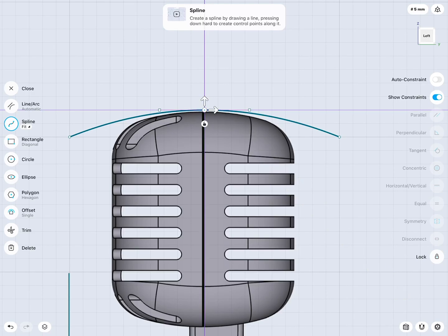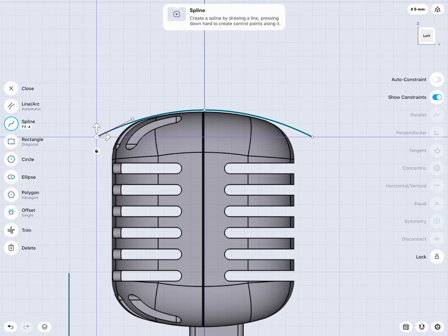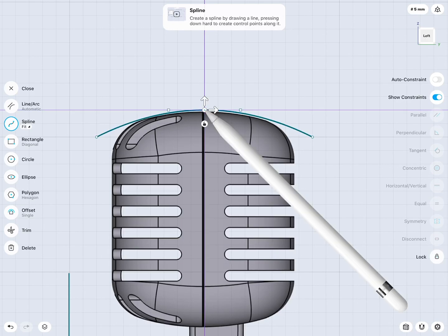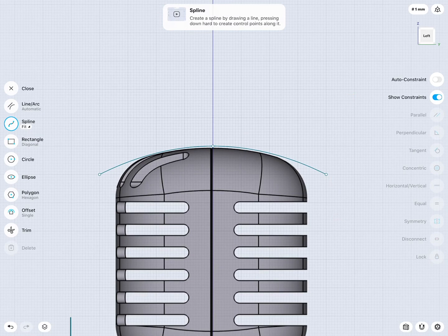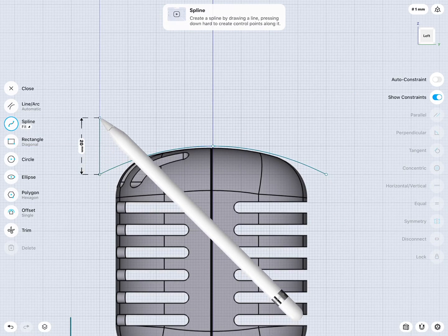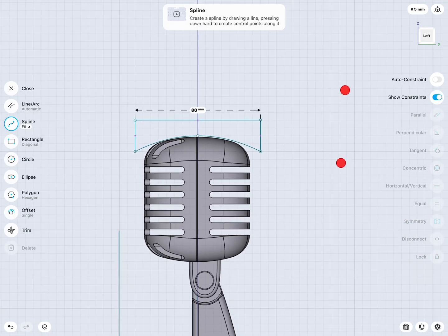The nice thing about the fit point is, as you can see, the spline runs through the points, while with the CV curve only the start and end points are on the spline, and the points in between are interpolated. So they all have their ups and downs. But here this was very easy. It's a nice curved arc-like spline I need, so the fit point is ideal. Now I need to close this, so I draw two lines up and go over there. Very good.